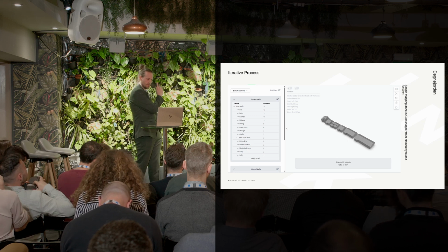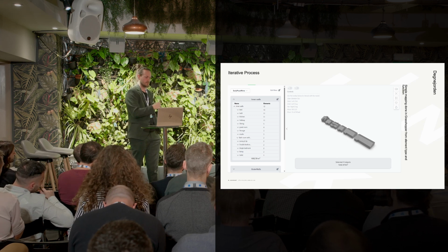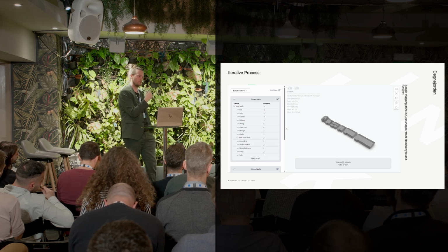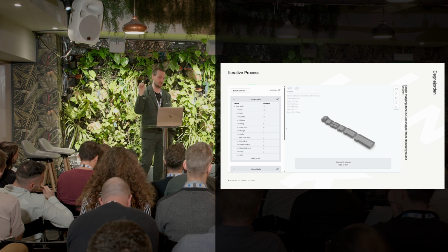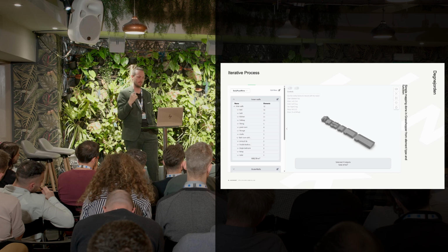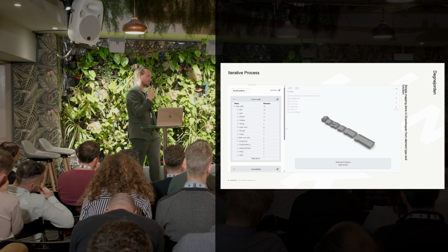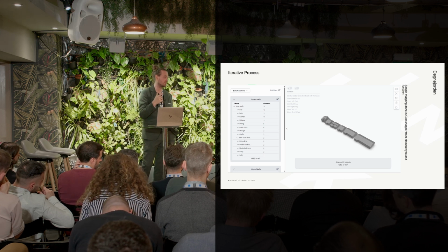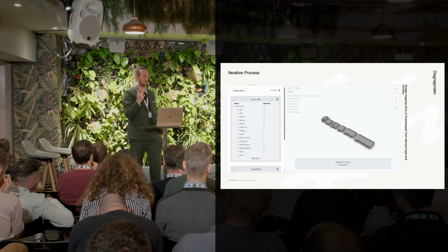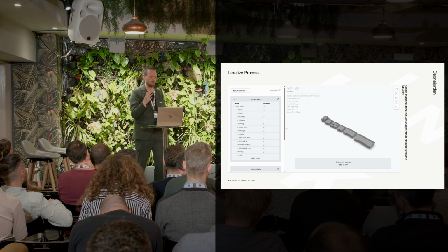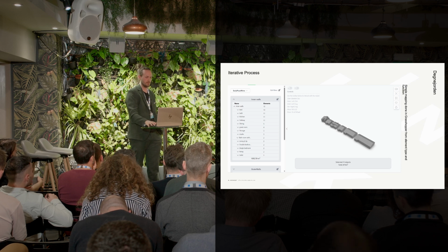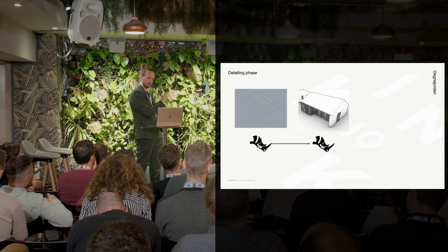And this is our view inside of the application, and you can see that for the interior walls, we start to have functions. Because when we're doing it with AI, you also get the room functions. So you get, this is a bathroom. A bathroom usually has a gypsum wall that is waterproof, so that's higher emission. And if you have a kitchen, you can start to use better dummy values because you have the area of the kitchen, and there will be a stove and some heating, plumbing. You can get some better values that are more concrete. So that's the process for the early phase.